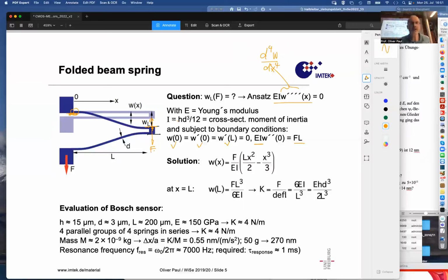And that is the case when it is thicker, because I have force per thickness. Thicker, the force distributes over a deeper, or higher, beam, so it will bend less. If the beam becomes thicker because D becomes thicker, then it resists the bending better, and it does so with the cube of the thickness.